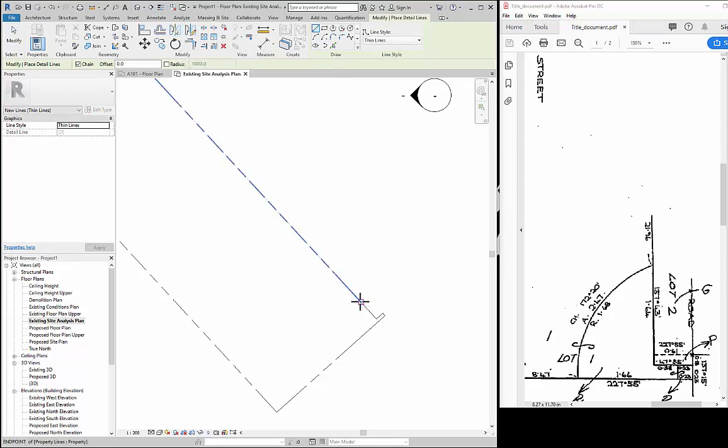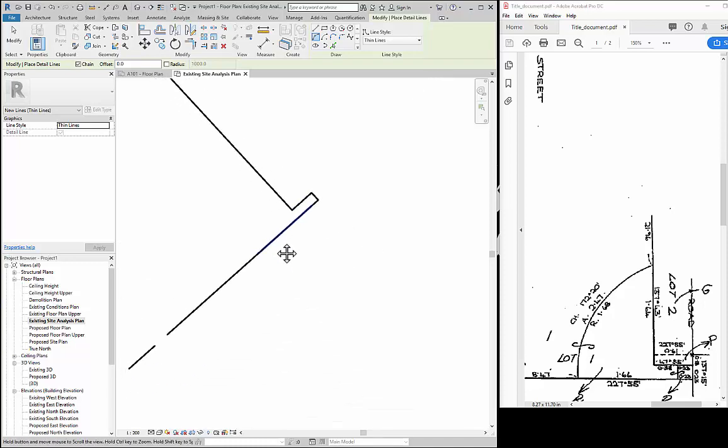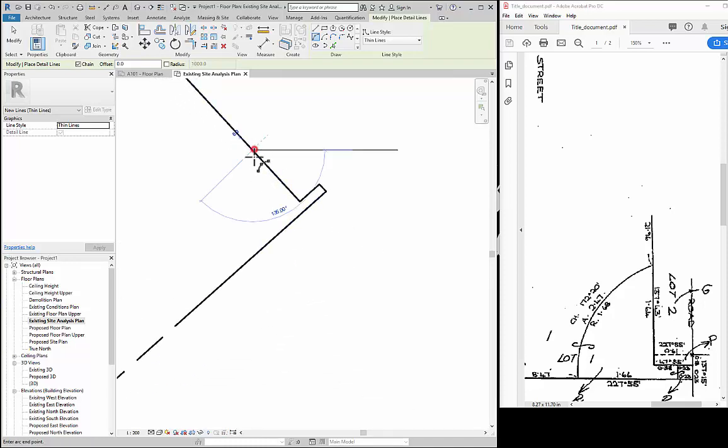You can see the end point hopping up there and there. I'll do an arc between this point and this point here. We'll do that as an arc. As you're going backwards and forwards, you can see the number that's changing. That's the one that we'll edit if we start typing in.